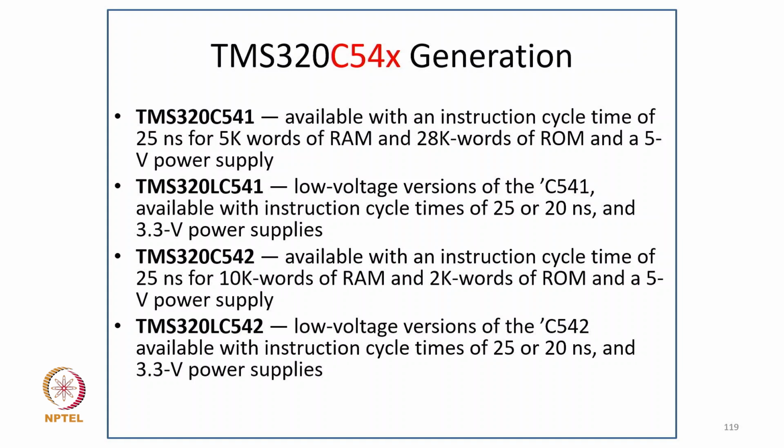TMS320C541, available with an instruction cycle time of 25 nanosecond, 5K words of RAM and 28K words of ROM and a 5 volt power supply. TMS320LC541, a low voltage version of the C541, available with instruction cycle times of 25 or 20 nanosecond with a 3.3 volt power supply. And